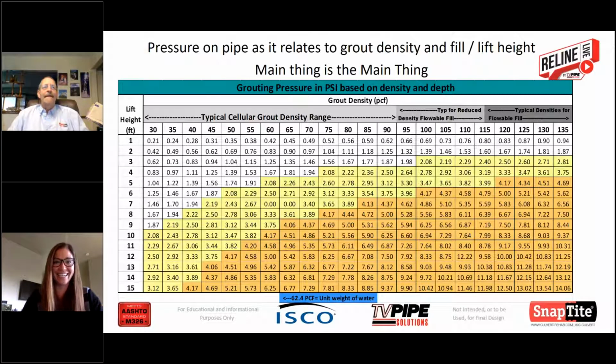First, we'll talk about thermal expansion and contraction, and polyethylene does have a very high expansion and contraction rate. A good rule of thumb is it's going to grow 1 inch for every 100 feet for every 10 degree temperature change. Obviously, you are putting some heat into the system when you pour the grout because it has an exothermic reaction. Typically, there will be enough frictional interface between the pipe and the grout once it is cured to limit axial movement.